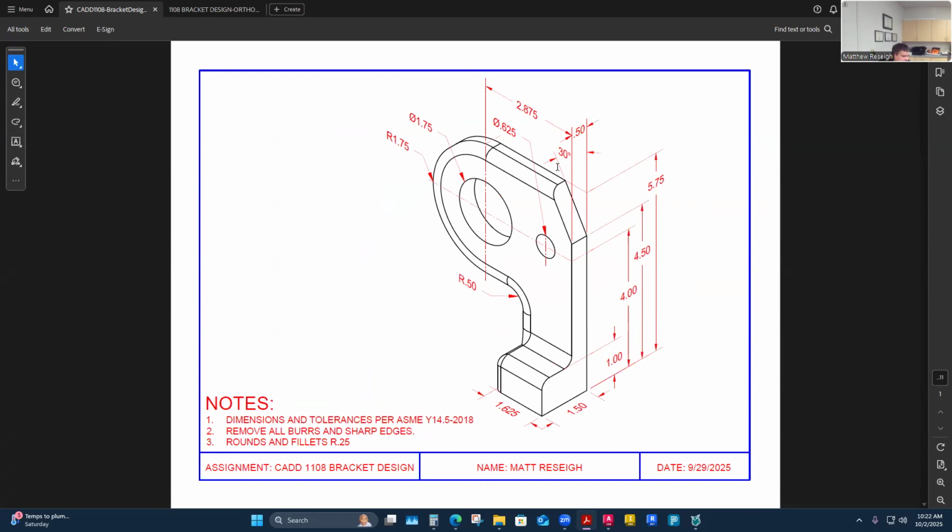I have a two decimal place dimension style, but when I look here, I have a mix. I have 2 decimal places, and I have 3. I do not want to round those and start causing inaccuracy from what I was provided to what I'm going to deliver to someone else.